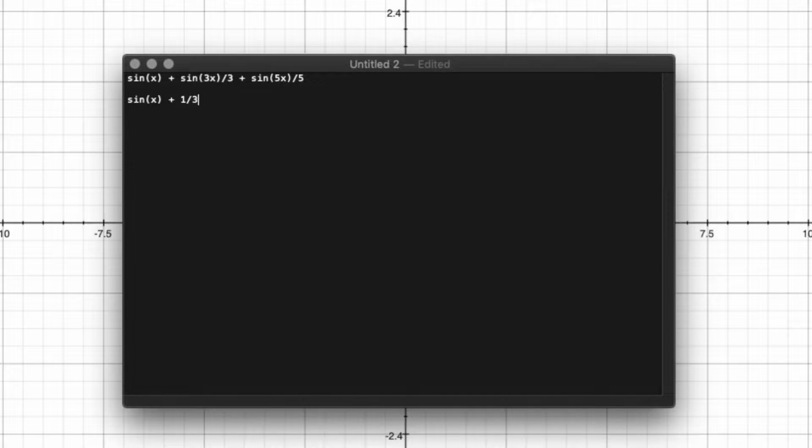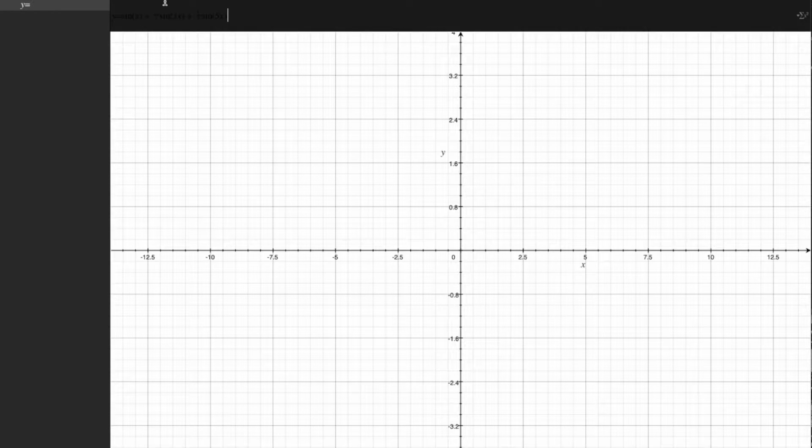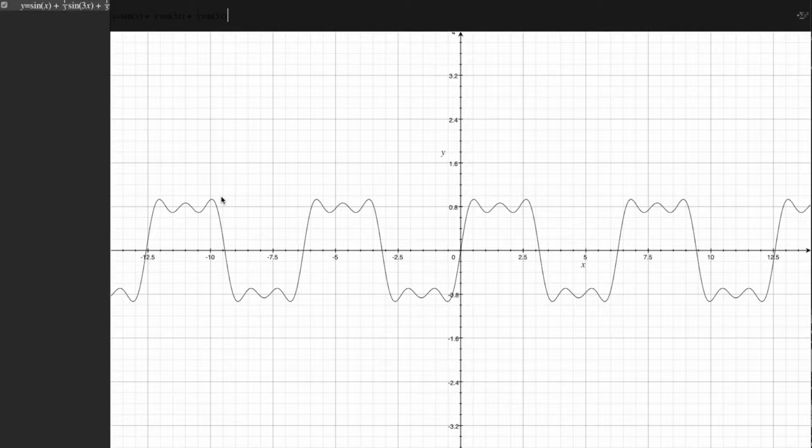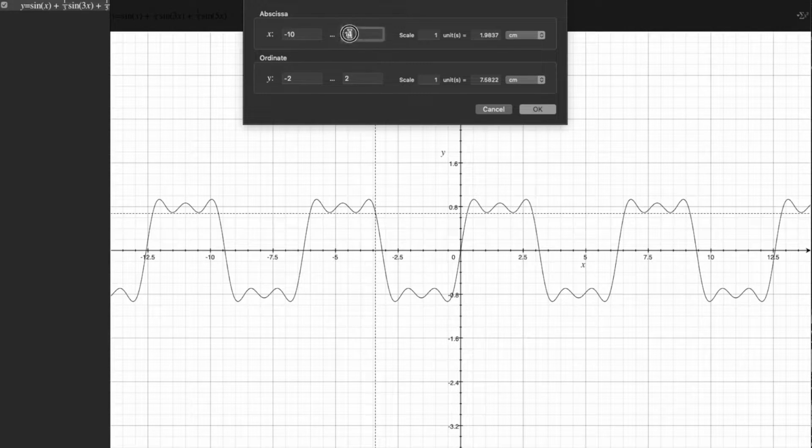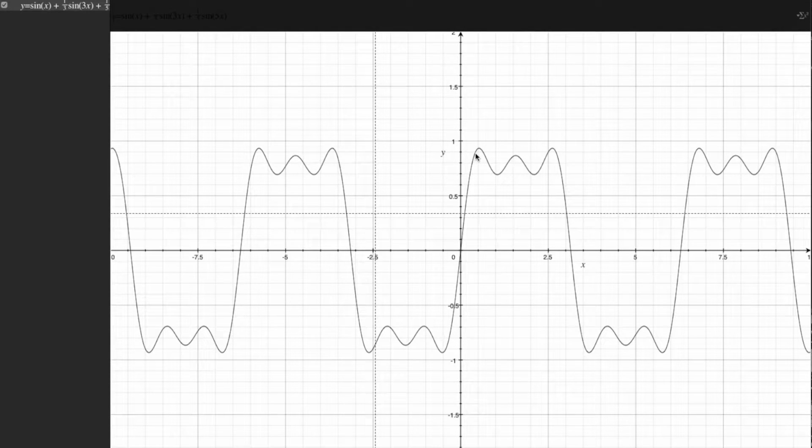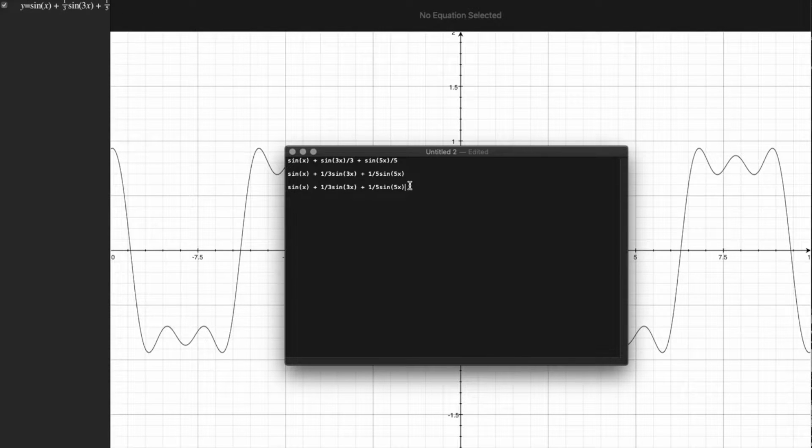Now, if you want to draw that in a way that the particular calculator I'm going to use will recognize it and do anything coherent, we have to kind of rejigger the equation a little bit, but don't worry about that. I'm just going to use the graphing calculator that's built into macOS. And if I paste that in here you can see 5 harmonics. This is the representation of a waveform that we get. So this is as square as it's going to look up to 5 harmonics.